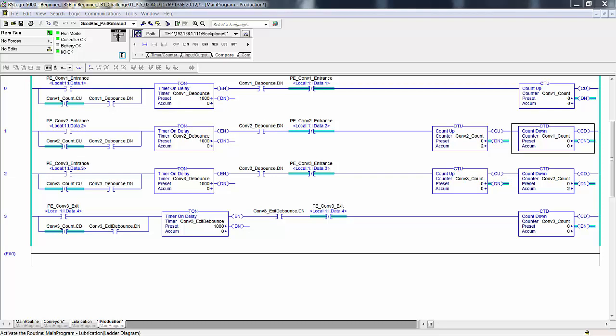The problem with that is if the length of your conveyors aren't well synchronized with the length of your cartons, you could end up with a situation with 3 cartons on a conveyor. A new one arrives at the entrance, the motor takes off, the leading carton breaks the photo eye of the next conveyor, but the 4th carton coming on to the entrance isn't clear of the photo eye. The conveyor stops and there the carton sits half on, half off. Or count each carton as it is transferred and then count them off when they transfer into the next station.